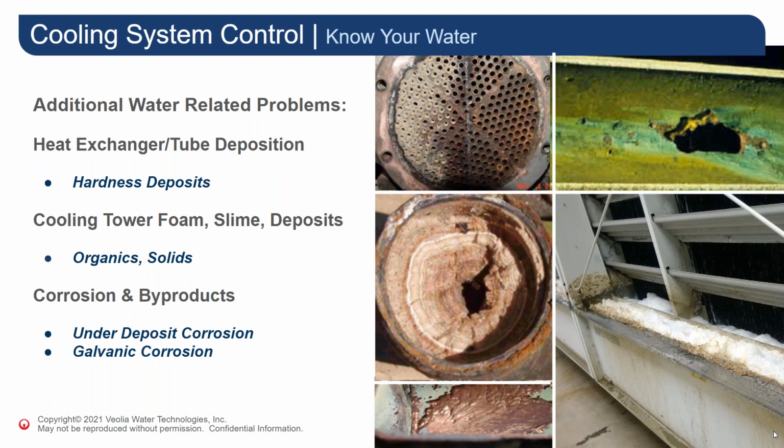Note the deposits in the upper left-hand photo. On the left side of that photo of a multi-pass exchanger, where the temperature is higher, you see more calcium being deposited in the tubes than you do on the right-hand side, where the inlet water is of a cooler temperature.